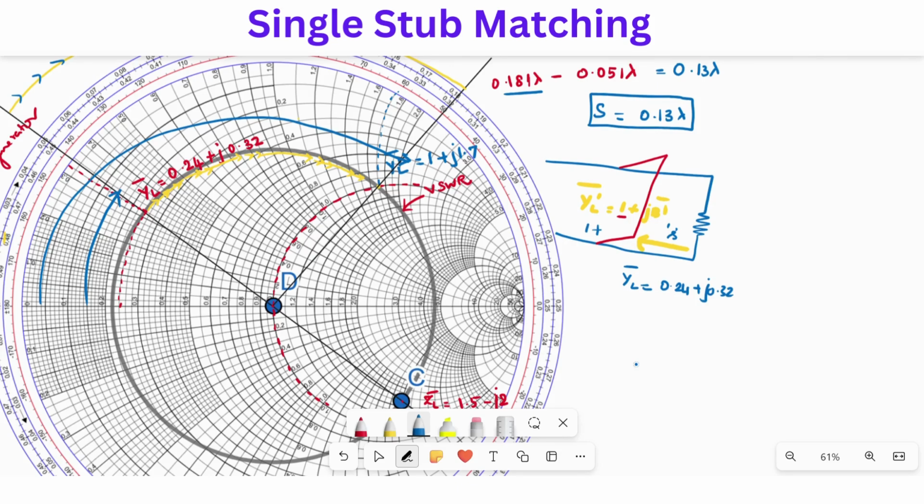1 plus J 1.7. As we have mentioned earlier, YL bar should be equal to 1. Only then the impedance will be matched. So what should we do? Here the YL bar is given as 1 plus J 1.7. So this 1.7 should be made 0. How can we make it 0?